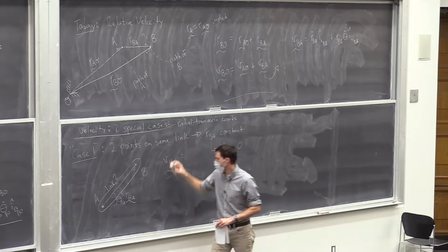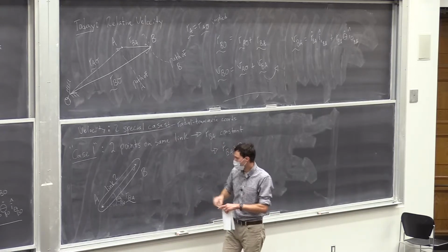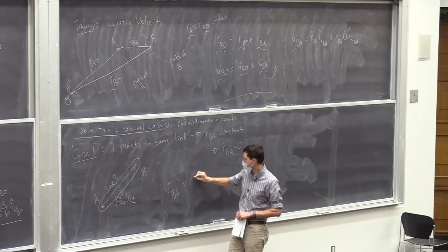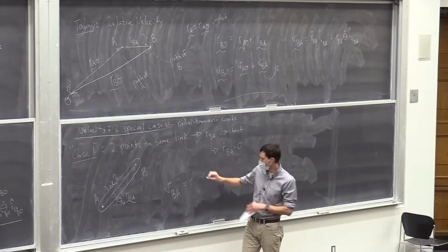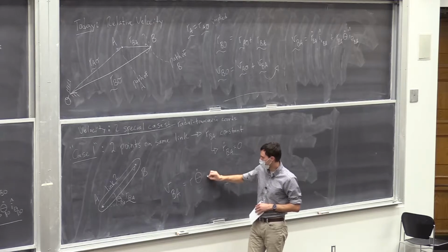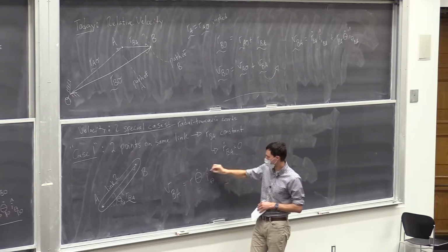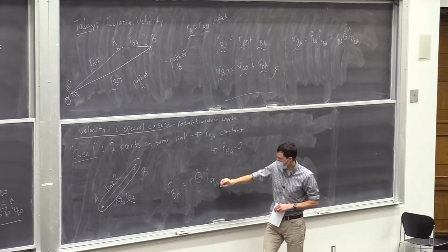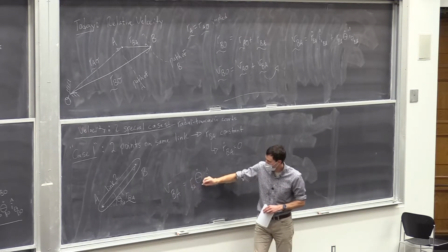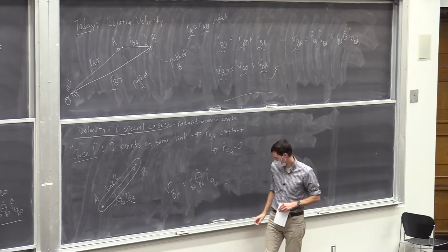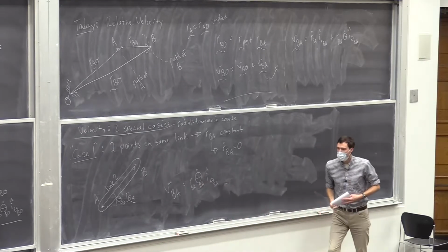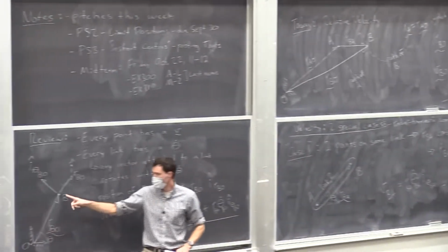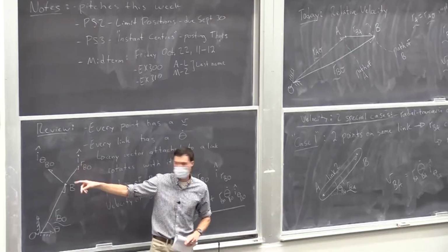So we can express VBA. It only has the single transverse component now, which is r, that's the length, times theta dot, and it's in the transverse direction. I'll add my subscripts, BA. Okay, and as always, when we write an r vector, we can immediately put these radial and transverse coordinates on it.